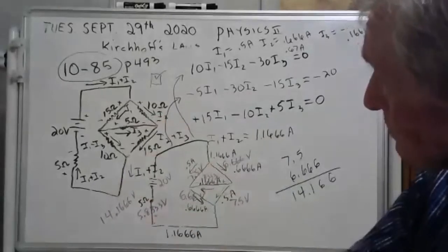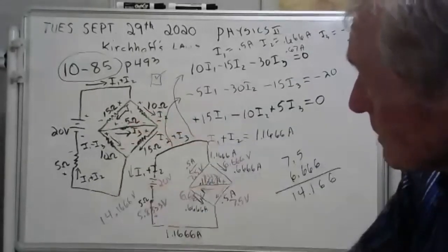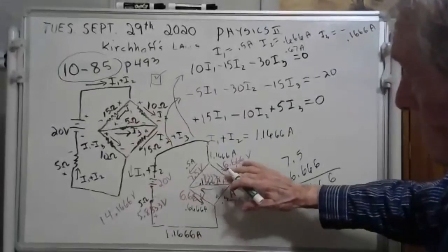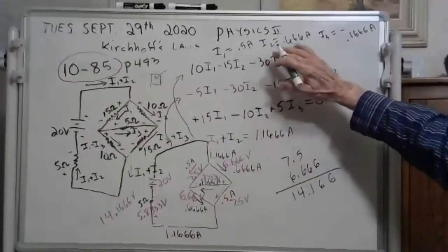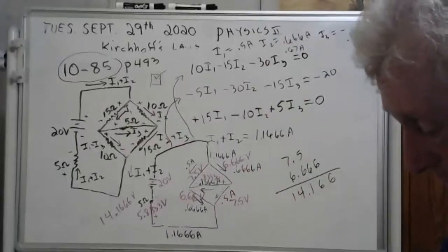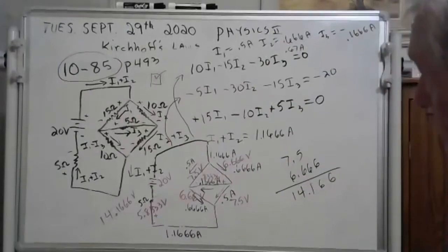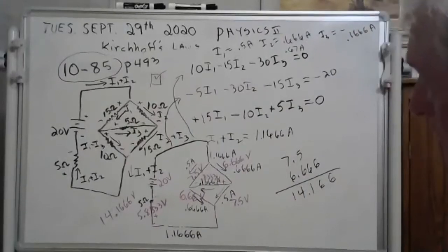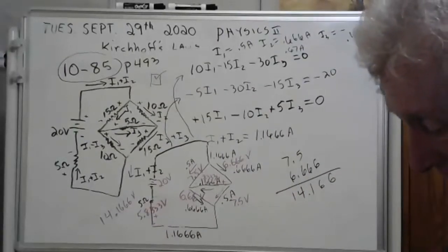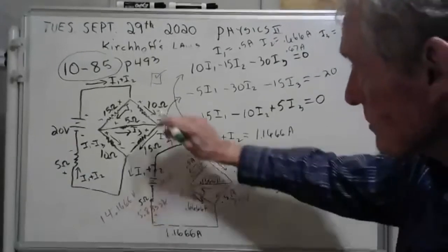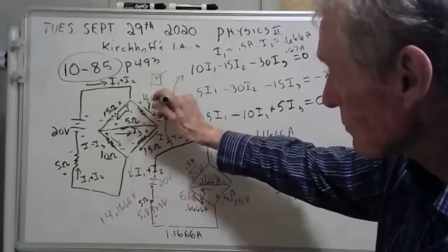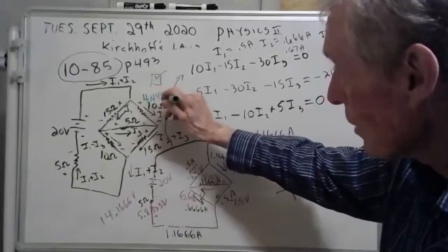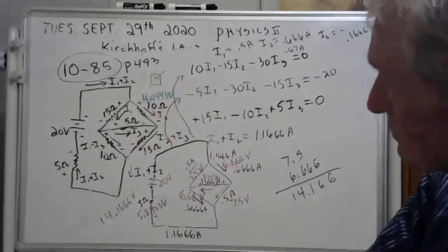What is the power on that one? See this one here? Well, the volts is 6.666 volts, and the current is 0.666 amps. So we're going to get the power. Here we go. You don't have to use this particular equation. You can use any of the three. They all give you the same thing. I'm getting a whole bunch of 4s watts. 4.444 watts on that one.